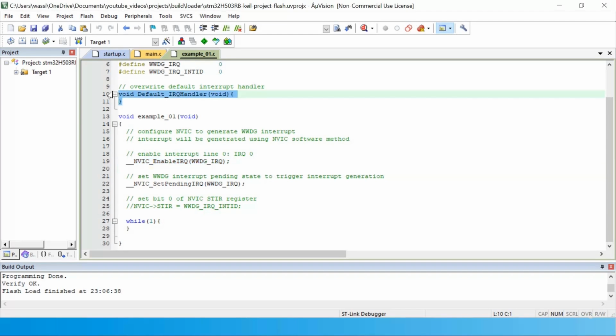The main goal of this project is to demonstrate how our CPU will boot in thread privilege access level, and then how we can switch from thread mode to handler mode. As we will see later on, in handler mode we will be executing in privilege and will be using the main stack pointer, and in thread mode we can use either the process stack pointer or the main stack pointer based on the control register value.